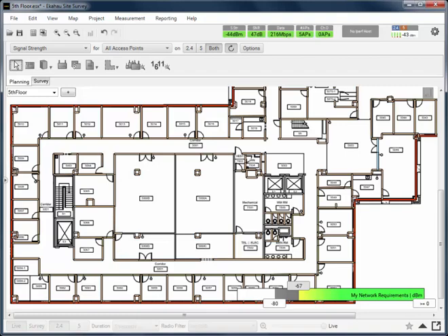After scaling the drawing, you typically begin outlining the floor plan with selected wall types. Ekahau has a wall outlining wizard called WOW, which allows you to open AutoCAD DWG files, map layers to wall types, and then have the wizard automatically create the walls. I'm showing the manual method here though. Most of the walls have already been outlined, but I left a few off.